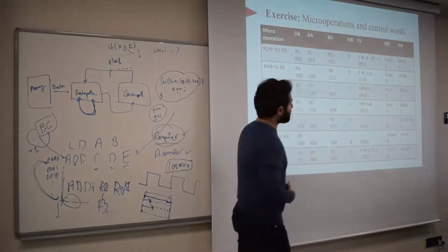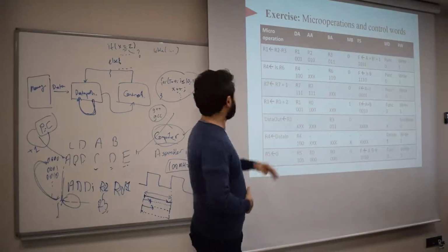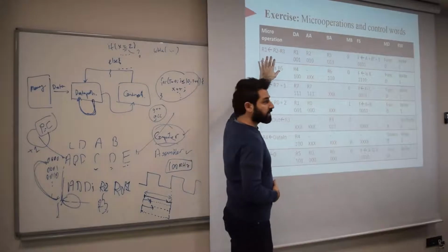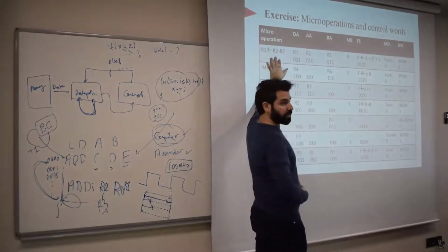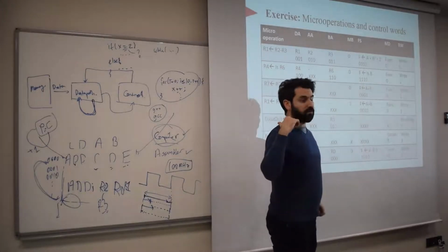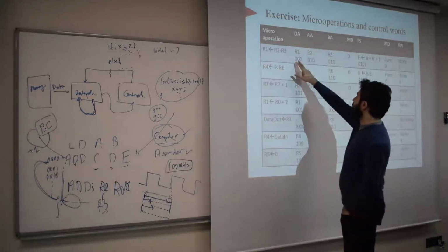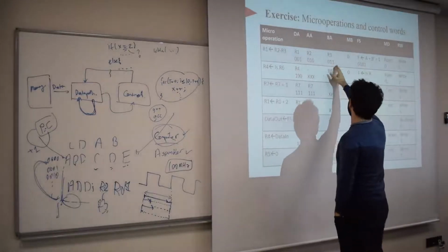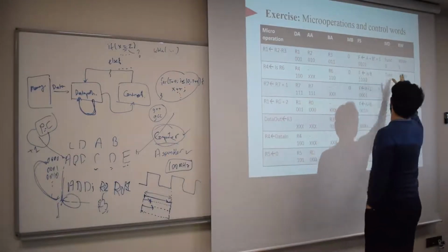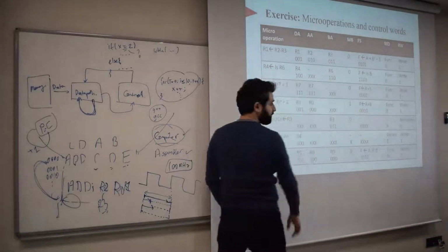Okay, so you see the control word is constructed by just looking at the instruction. There's a one-to-one map. Once the operation, or instruction, is given to you, you can generate the control word by using the tables. Okay? So you can see here, our control word is 001, 010, 0110, 01010, and 1. Okay? Similarly, you can do the same thing for left shift.